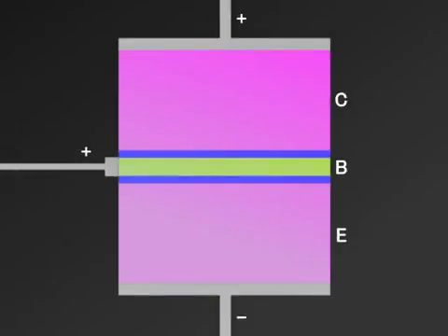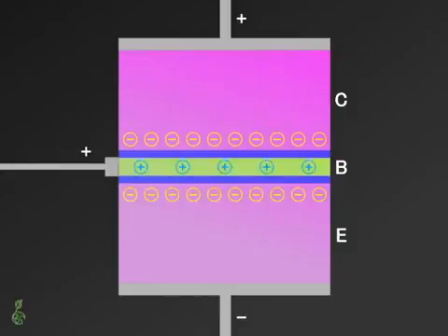A transistor is made up of 3 layers of a semiconductor material which have been doped differently. An NPN transistor consists of a layer of p-doped semiconductor material sandwiched between 2 n-doped layers. The n-doped layers contain free electrons. They are called collector and emitter. The base is very thin, and it contains holes that are also called defect electrons.